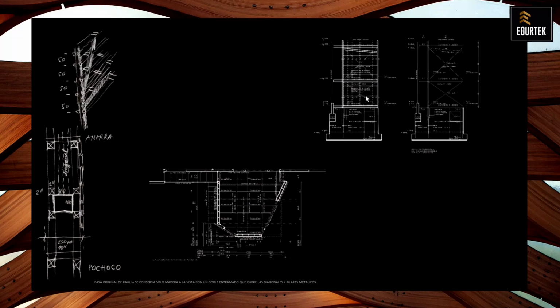diagonal struts. Timber was used for bracing previously, but since the old house was completely timber, a metal structure was much better for the tower. This is 100 by 100 millimeters, and there's a double casing. In this case, it's separated into two casings of 2 by 2 that go outside the metal structure and outside the diagonals and offer a continuity of timber.